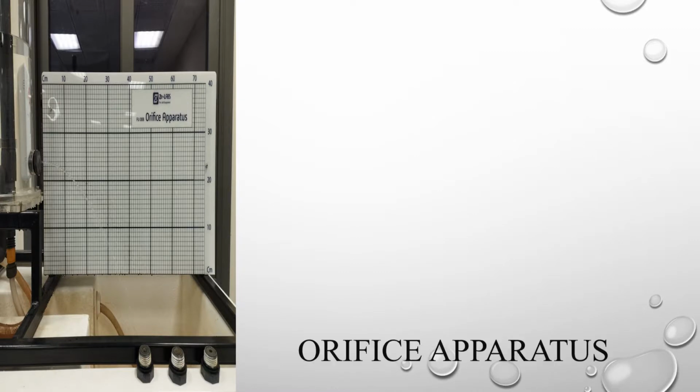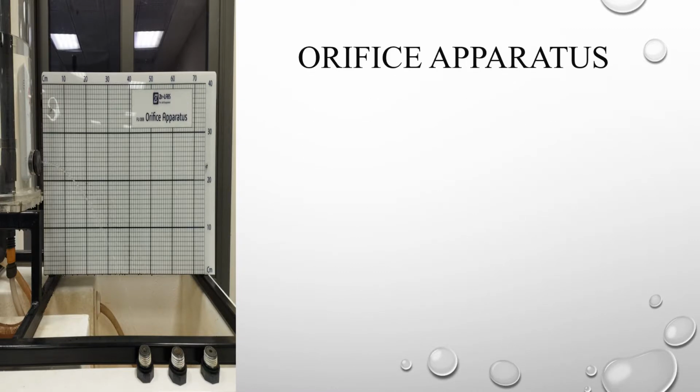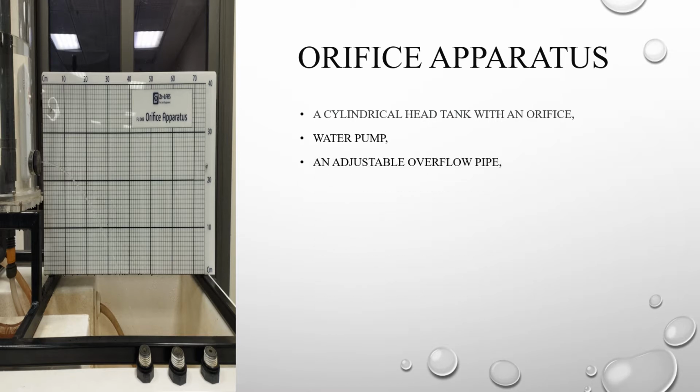The orifice and free jet flow apparatus consists of a cylindrical head tank with an orifice plate set into its side, and a water pump to maintain a steady level of water at the reservoir's surface. An adjustable overflow pipe is adjacent to the head tank to allow changes in the water level, with a flexible hose attached to the overflow pipe that returns excess water to the hydraulics bench.